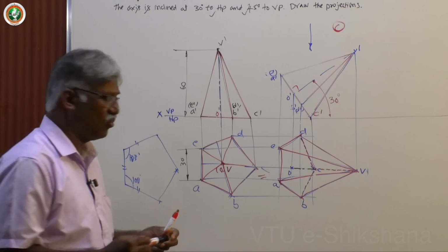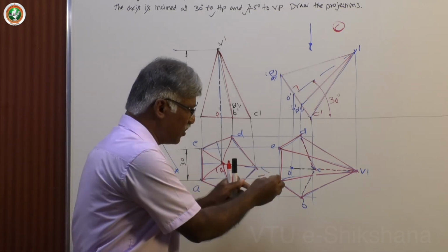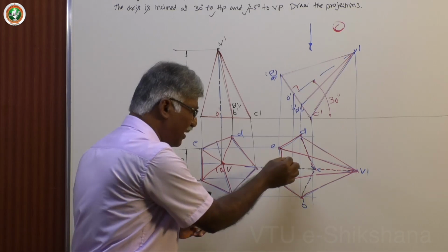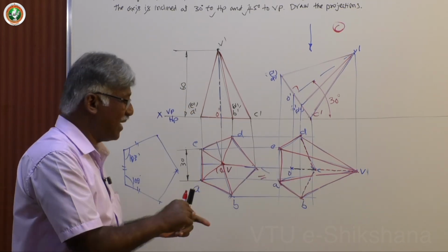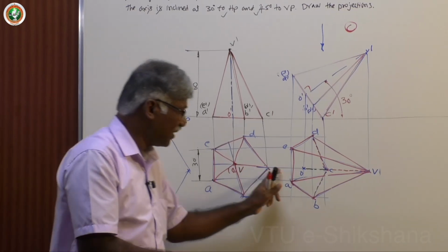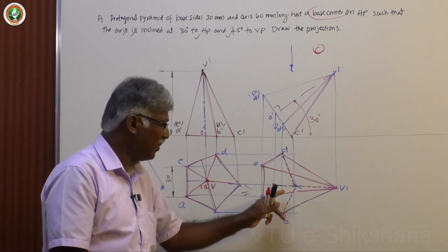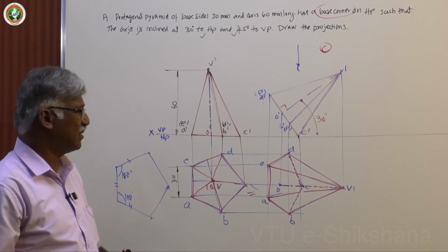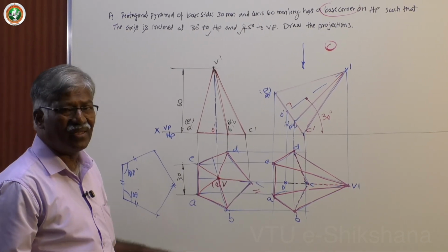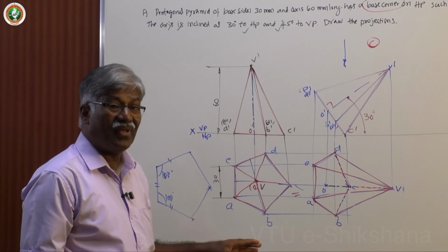Okay, you can use 0.25, 0.35 in the computer, and what best you can do is zoom in on that area and remove whatever line is available, then replace or modify that. Suppose the continuity line is there, then you have to go for split, otherwise you use trim, then you keep these 2 out, then you can replace that with the axis. So, this is how we can complete the second figure top view of the problem.